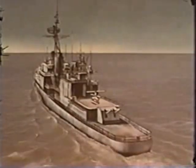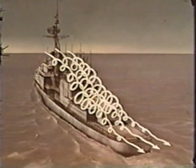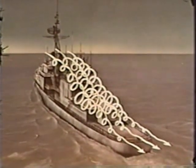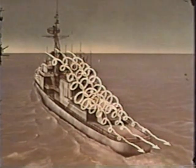Winds from the bow or the quarter cause the least turbulence and may therefore range up to 30 and 40 knots. The ship should maintain a heading that will put the relative wind on the bow or on the quarter. If the wind is directly ahead, the ship's superstructure causes maximum turbulence. Most of it is vertical, and the downward forces are detrimental to flight operations.